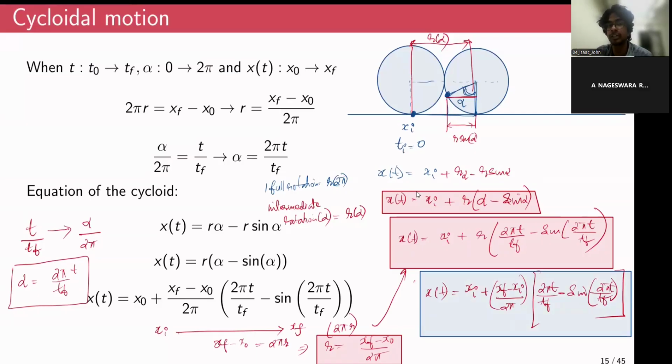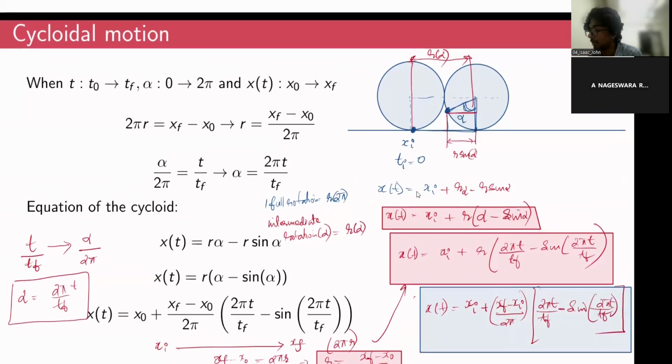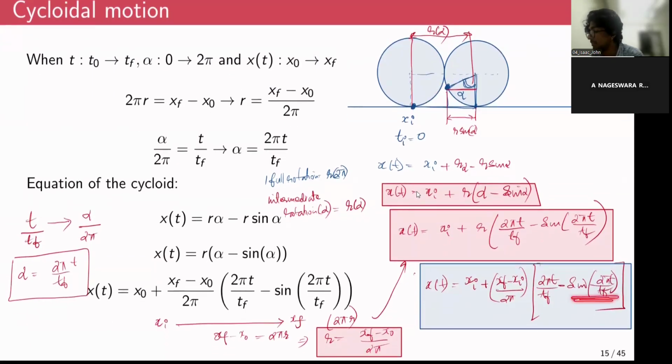The cycloidal motion is also very smooth, right? As you can see, the locus of all the points would be something like this. It's basically very smooth, right? And due to the fact that we have sine terms inside it, the derivative would be cos. If you take a derivative further, it'll again be sine and cos terms. So in that regard, the position is smooth. Velocities would also be smooth. Acceleration would also be smooth, just like a sine or a cosine curve. It'll be very smooth.